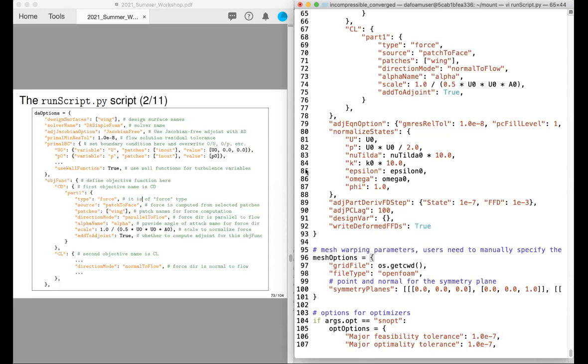If you overlap a little bit, that should be fine. The bottom line is that the FFD point blocks could slightly overlap, but make sure that your design surface geometry does not belong to two different FFD blocks, because that will impact how the geometry is snapped to the FFD points.